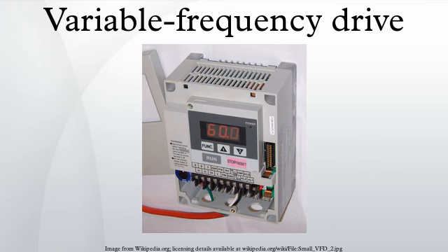putting high stress on the cable and motor windings and eventual insulation failure. Note that standards for three-phase motors rated 230 V or less adequately protect against such long lead overvoltages. On 460 or 575 V systems and inverters with third-generation 0.1 microsecond rise time IGBTs, the maximum recommended cable distance between VFD and motor is about 50 m or 150 feet. Solutions to overvoltages caused by long lead lengths include minimizing cable distance, lowering carrier frequency, installing dV/dt filters, using inverter duty rated motors, and installing LC low-pass sine wave filters.